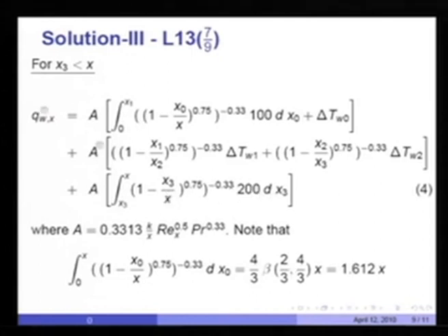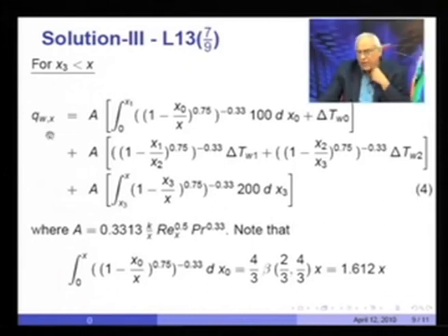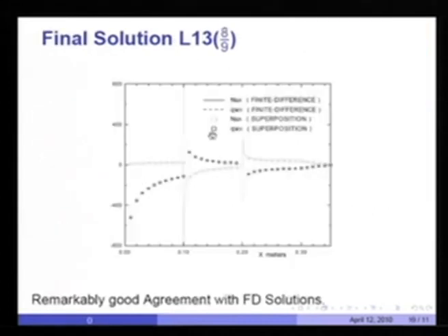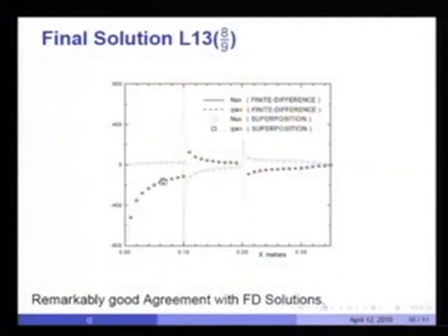So, this is how the solution will proceed, and I will get QWX variation for different segments of the solution. What do they look like? The squares show the variation of QWX. As you expect, in the first part, the wall temperature varied from 40 to 50, the free stream was at 90, and therefore heat was simply flowing into the wall, and therefore QWX is negative, but rising, because as the temperature difference goes on reducing, the amount of heat flow is also going on reducing.